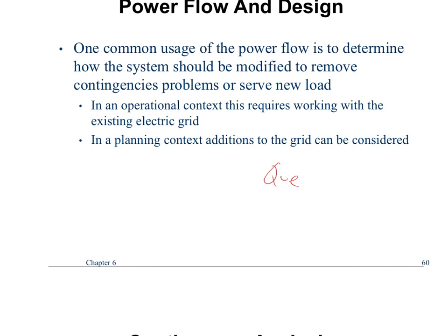And so whenever the analysis is happening for future projects that are after you, they have to include yours. So any changes that need to be made to the system as a result of their projects, you don't have to pay for. But any of the system changes your project imposes, you have to pay for those. And that could be very, very expensive, hugely expensive. So the New England Clean Energy Connect, why are they adding a bunch of 345 lines and adding breaker positions and rebuilding certain sections? It's because they did this contingency analysis to figure out, okay, if we lose this line, what's going to happen? And so that's what ISO New England has done.